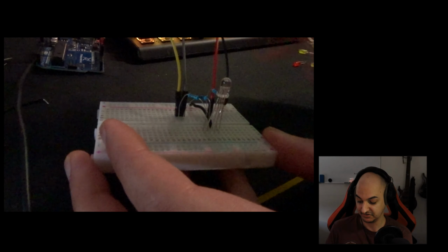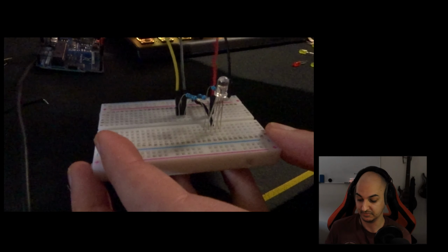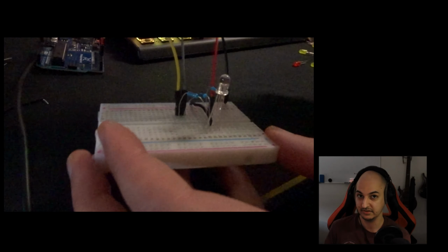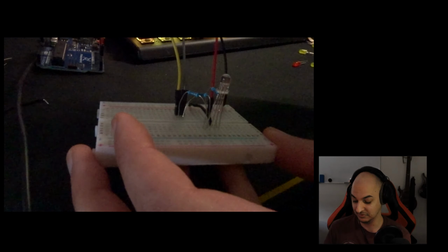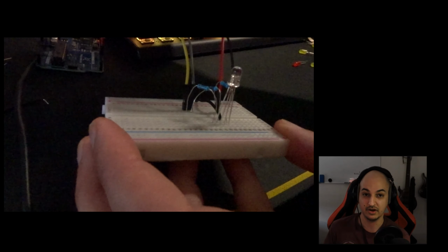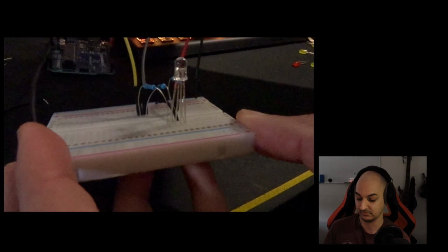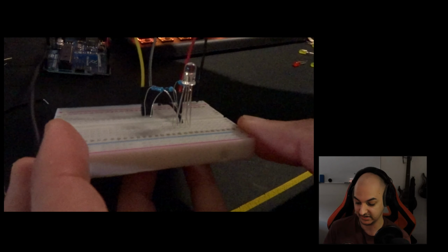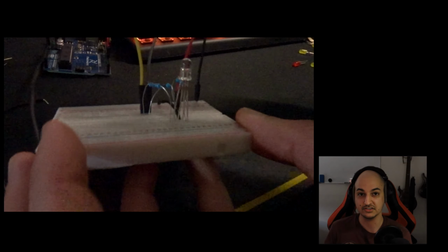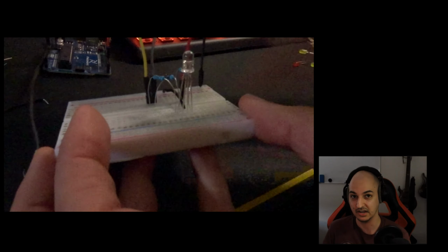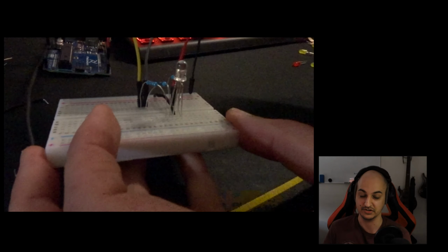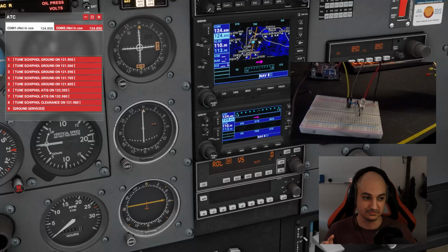Green, which is pin 2, is wired up to pin 5, and then blue, which is pin 4, is wired up to pin 6. The second one is going to be the common cathode line, which is going to go to ground. So pretty simple setup. And let's see how we can use this to display different colors.